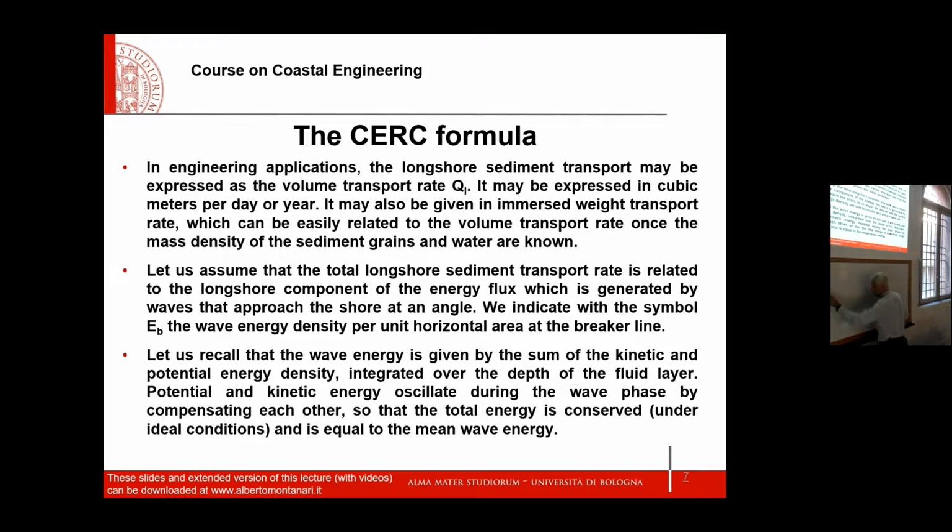If I have a coastline here, typically a plane wave approaches the coastline at an angle. What is this angle? It is the acute angle alpha between the wave direction and the coastline. So if I have in this wave direction a cross-shore component, I may expect a cross-shore sediment transport component. If I have a longshore component, in the same way, I can expect a longshore sediment transport.